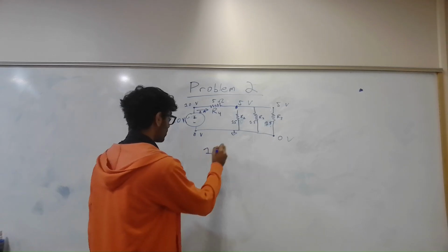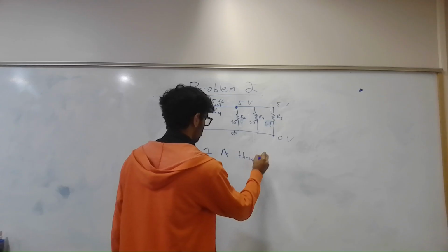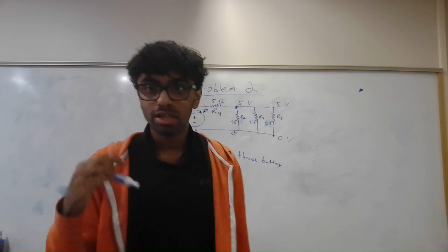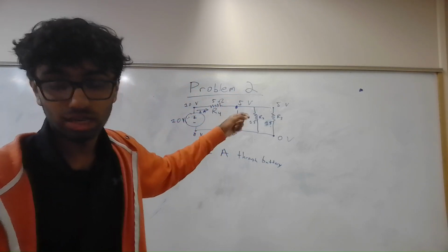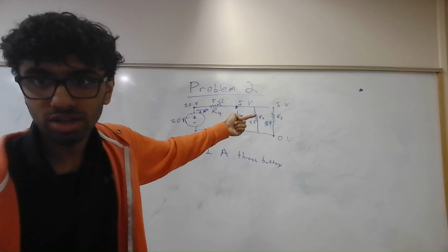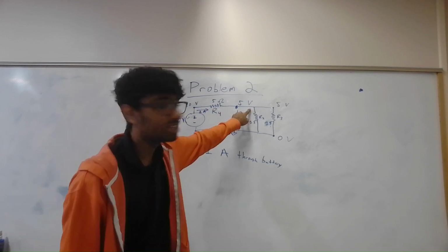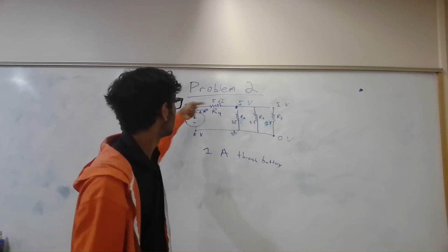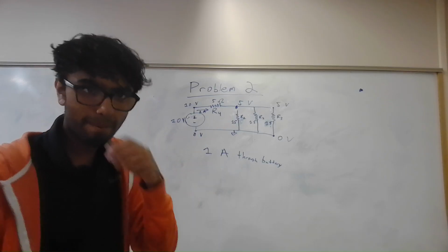So 1 amp of current through the battery because the same current flows through this resistor, and that's one of our key assumptions, that along a single wire, which is what this is, the current can't change, okay? Even when there's resistors on that wire. The current can change, indeed it does, here, right? But not from here to there, because that's along the same loop, okay?